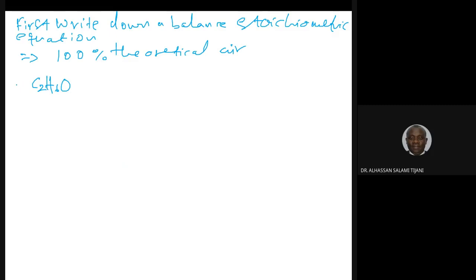What is the amount of C2H6, the ethane that enters the combustion chamber? That is 10%, so that gives 0.1 kilomole, plus, the fuel also has 90%, 0.9 kilomole of C8H18. Then we have the air. We don't know how much air enters, so we represent it by the theoretical amount of air.